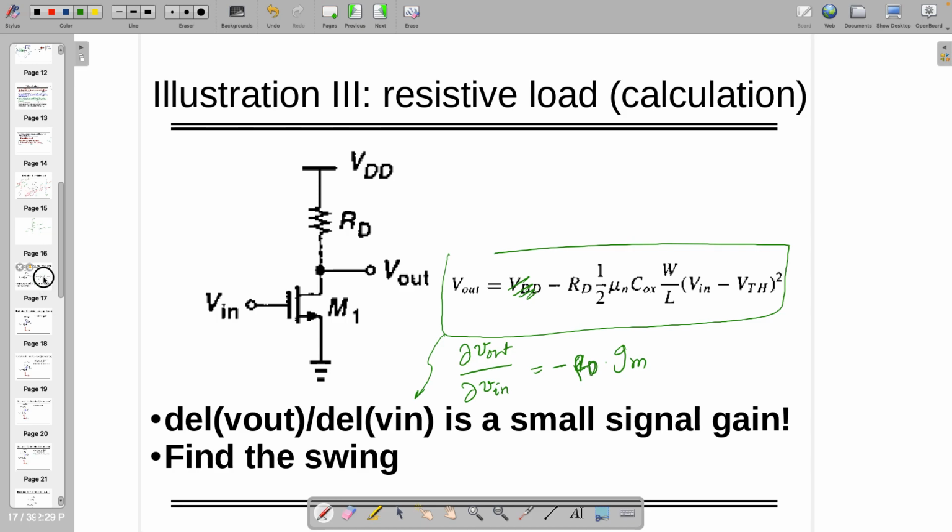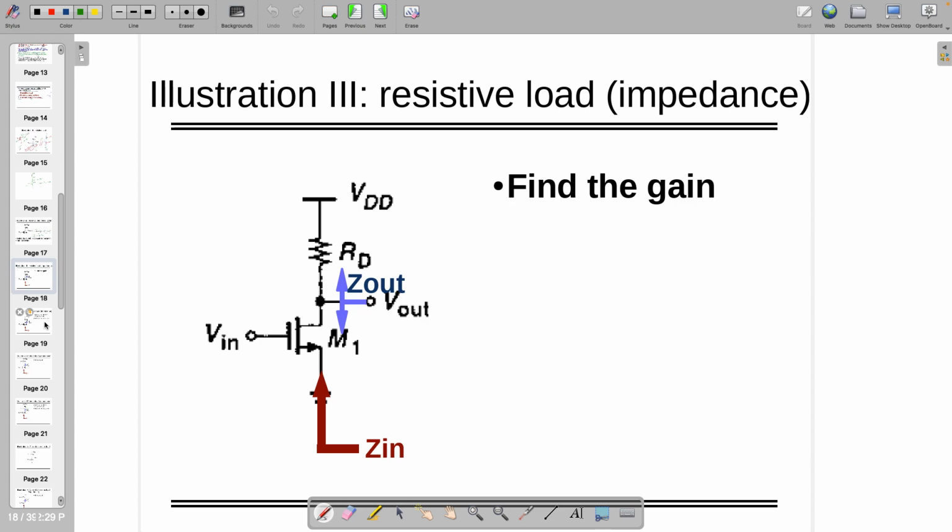This is that technique I just kept, which is given in the book, and the book is solving all the amplifiers like this. I assume that you studied this in your previous course, so we'll go with this technique and trick. If it is required, we will revisit that whenever it's required. So as I told you, if input is available here, and if you're looking from this side, what is the impedance looking from the source? 1 by gm in shunt with RO, you can approximate to 1 by gm.